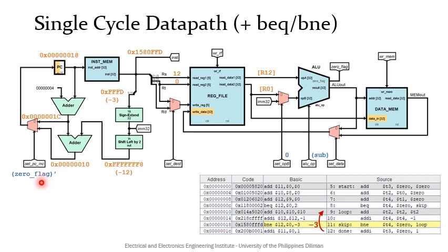Also for BNE, we are not writing into the memory nor the reg file, so the write enables must be deasserted. The control signals for the MUXes of the write path can also be considered as don't cares. We then expect that when the clock rising edge occurs, the PC should point to the next correct instruction and no other register or memory positions must be written to.